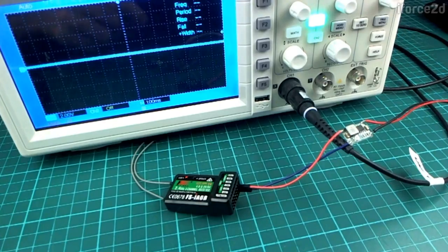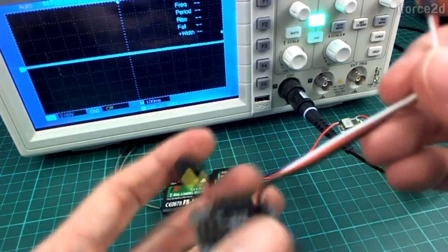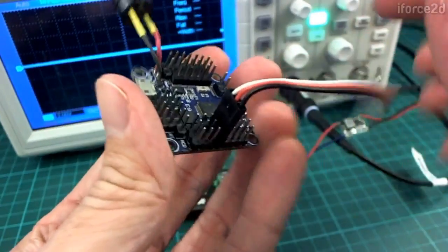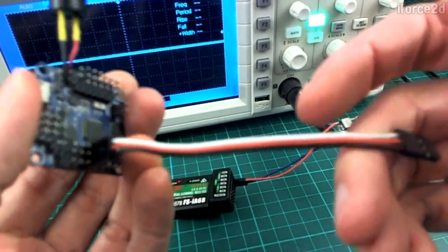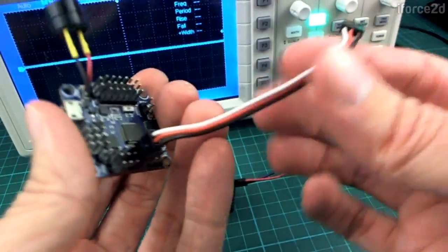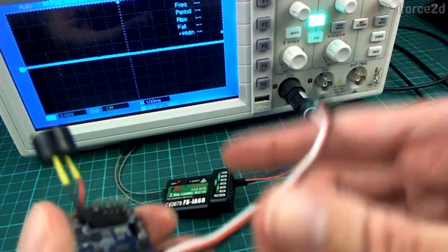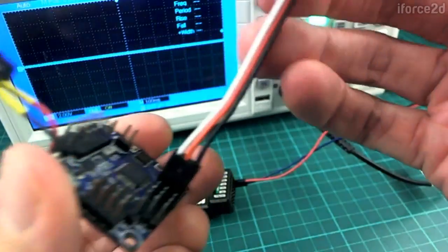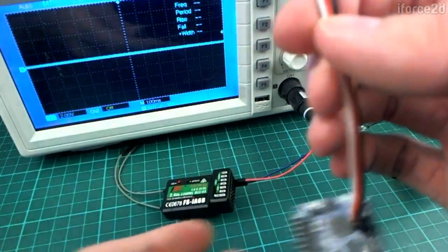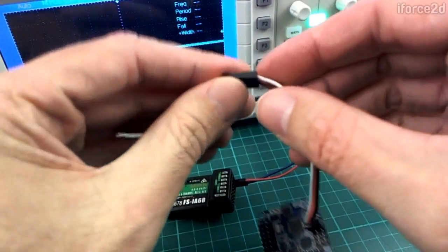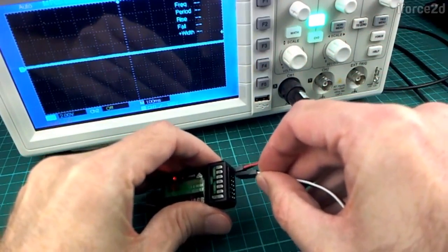But of course quadcopters don't have any servos. What we wanted to use this for is to talk to the flight controller like this. So we can use one of these servo cables to connect the receiver and the flight controller. There's no servos here, but we tend to call these cables servo cables for the reasons that I've just shown you. It's got 3 wires, and we're going to connect ground and 5 volts and the signal. And I'm going to put this into, let's see, was it channel 6 or channel 5?